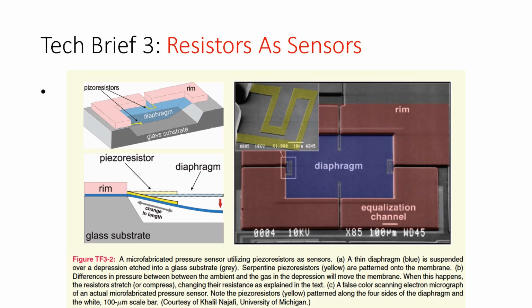And so if we look on the right, you actually have a picture from an SEM, scanning electron microscope, showing a microfabricated piezo sensor. And so these sensors are extremely small and extremely low cost, all things considered, and they give a pretty high resolution of location by stringing a bunch of them together. So there's a couple different methods. This used to be in not the new cell phones. The new cell phones are generally capacitive touch, but the old touch screens where you actually had to push on the screen and make it like a physical push, they had a lot of these piezo sensors.